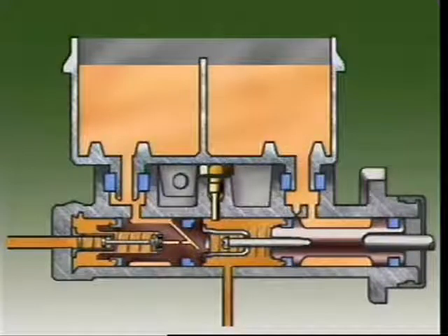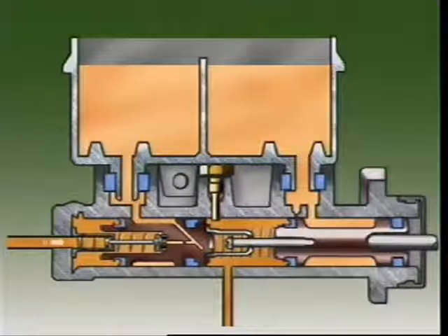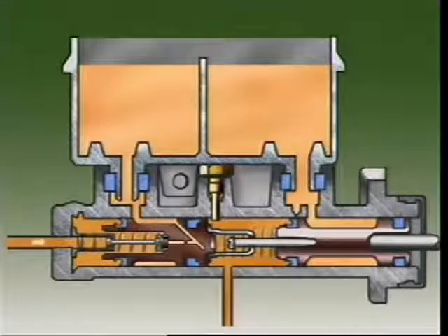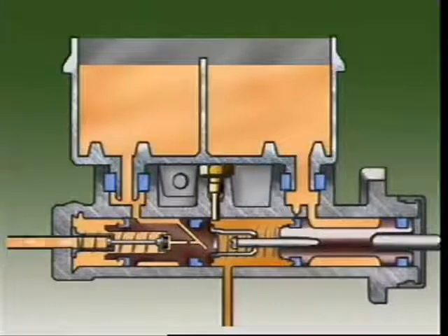If braking conditions are such that the hydraulic modulator must return brake fluid to the master cylinder, then for the front brake circuits, fluid is returned to the front section. This forces the secondary piston back against the force of the primary piston spring and the rear brake pressure. If enough fluid returns, the center valve opens and allows fluid to return to the reservoir.